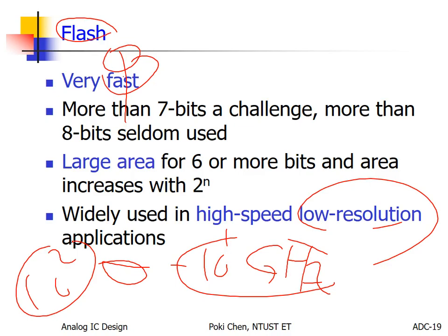But for your digital oscilloscope, they can claim their real sampling rate is 40 gigahertz or even 80 gigahertz. They have some kind of trick, which I will explain. They don't use a single ADC. We cannot make that; we are only humankind, not gods.